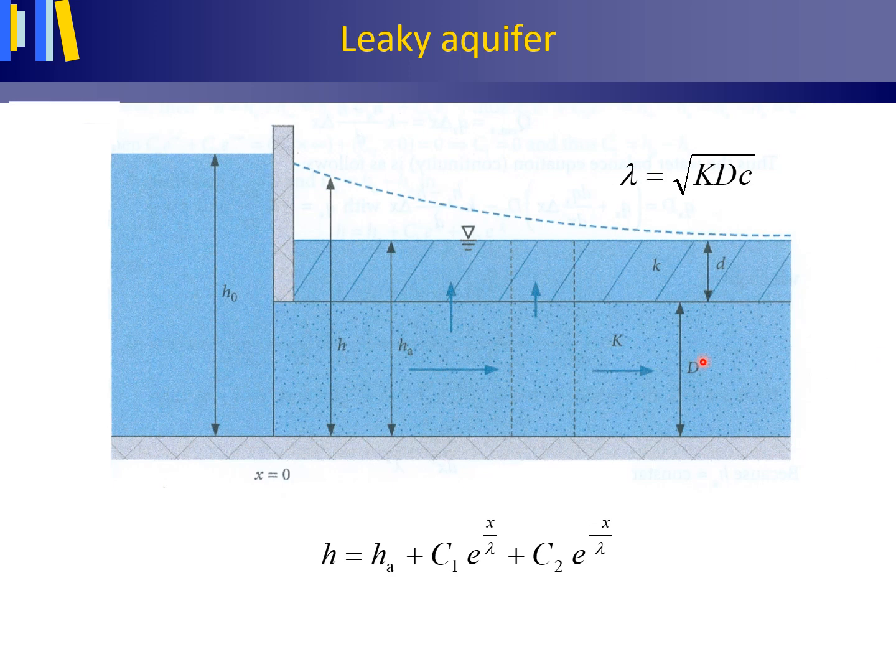Kd is the transmissivity of the aquifer, and C is the hydraulic resistance or vertical flow resistance in the overlying confining layer. C equals the thickness or depth of the homogeneously taken confining layer, small d, divided by the vertical hydraulic conductivity, small k, thus meters divided by meters per day giving days.